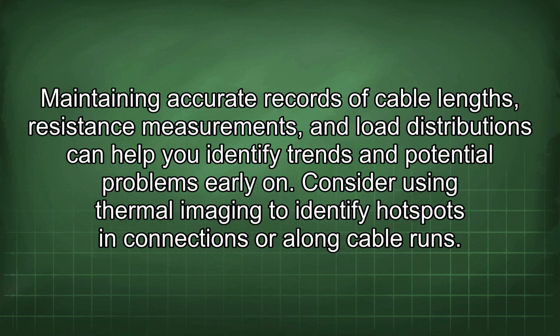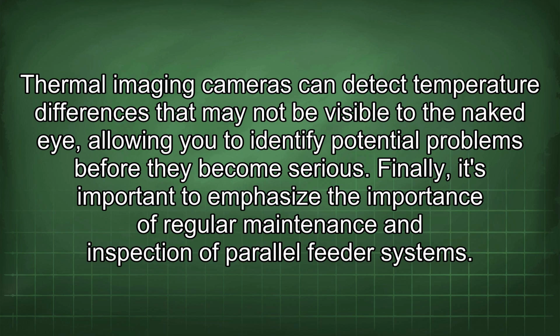Consider using thermal imaging to identify hotspots in connections or along cable runs. Thermal imaging cameras can detect temperature differences that may not be visible to the naked eye, allowing you to identify potential problems before they become serious.